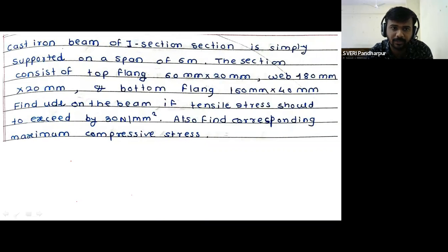and in that we discussed how the statement will be given, how the type of beam is mentioned in the statement. Or if the type of beam is not mentioned in the statement, then the sagging and hogging bending moment is mentioned in the statement. If the type of beam is not there, and the sagging and hogging bending moment concept is not represented in the statement, then we are unable to verify whether that beam is a simply supported beam or a cantilever beam. So we are unable to calculate sigma T and sigma C.